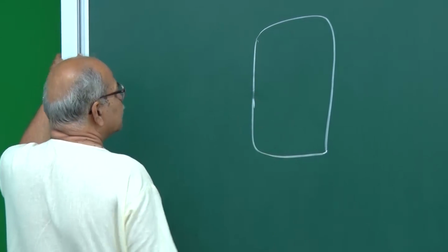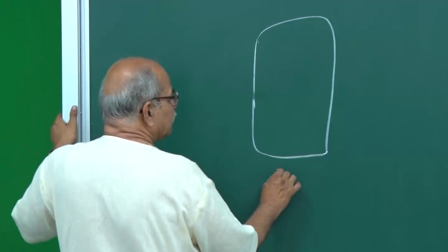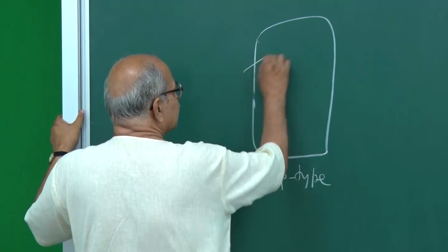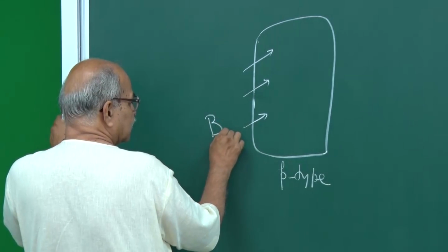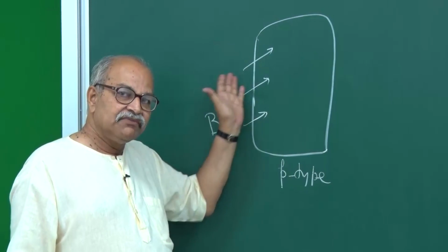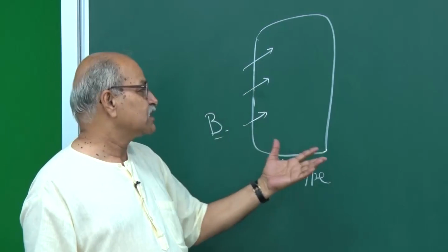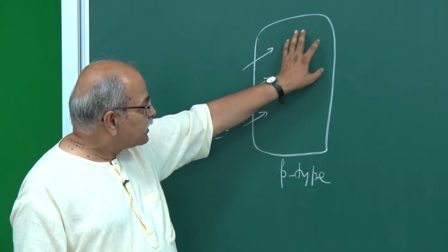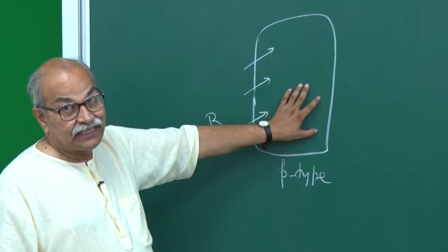So, that is the starting material, and with this starting material, the first thing is this entire wafer is made either p-type or n-type. So, let us say we make it p-type. To make it p-type, you have to diffuse trivalent impurity like boron. So, it goes there. Here also you have very controlled processes. There are several processes by which you diffuse these impurities, and at the end you retain that silicon crystal.